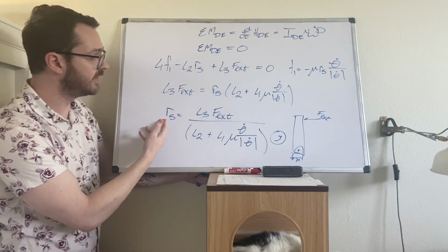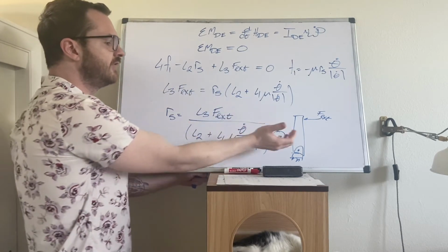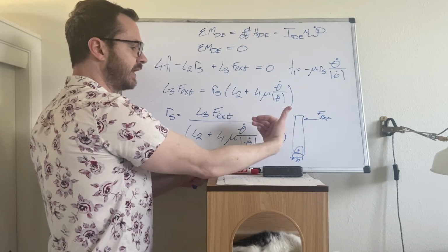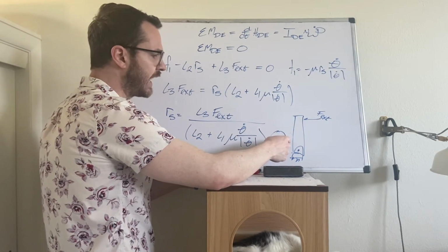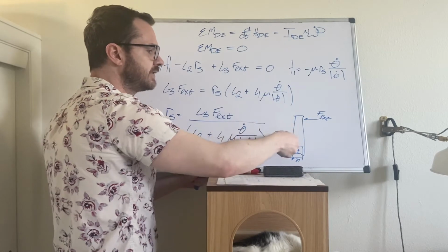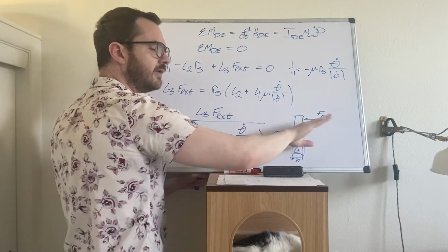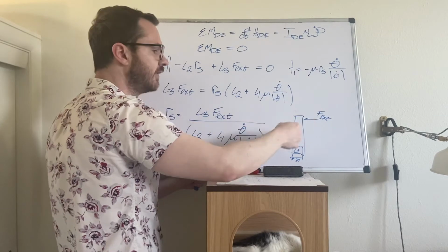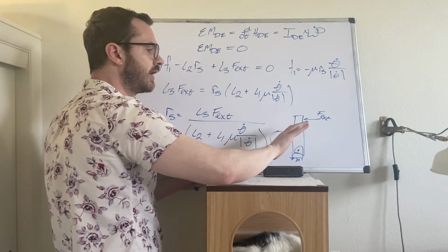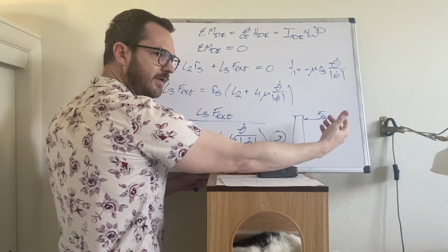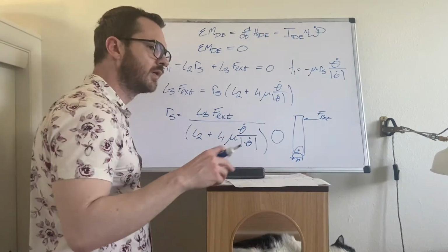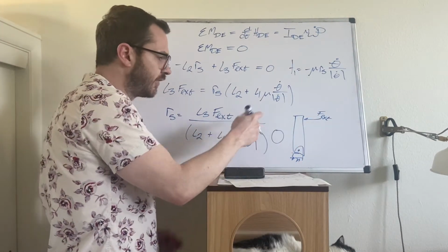So R5 is diminished. When your disk is spinning in a positive direction, it's going to reduce the reaction force here. It is actually kind of kicking the pendulum away from it, okay? The friction at that point would create a slightly positive negative moment to take this pendulum away. What happens if the direction of the disk reverses?